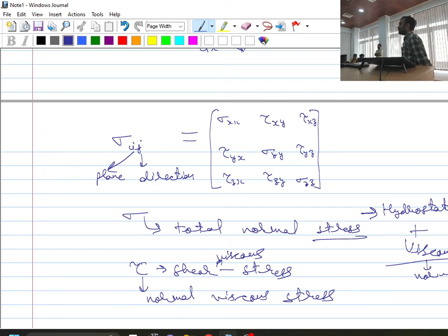For a Newtonian fluid, if I multiply the linear strain for a 1D element with the viscosity of the fluid, it becomes stress, not shear stress. Whenever I refer to the normal rate of strain, it becomes the normal viscous stress. Point is clear? You are just calculating the strain in the normal direction and then multiplying by viscosity.